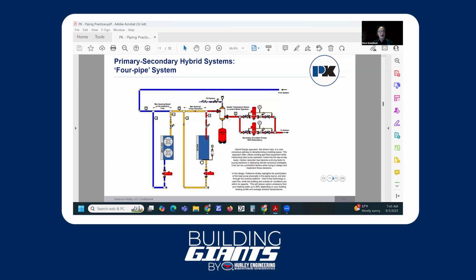So we talk about the ambient temperature and how we'll designate the appliances and what does what and how hot we're going to make that water. Well, during mild temperatures, so think mid 40s, heat pumps are super efficient. You can get a lot of output for very little input.